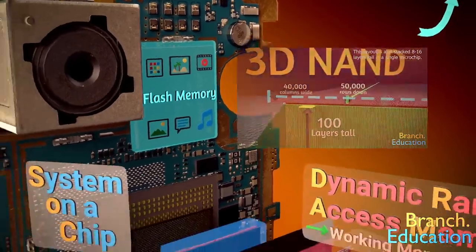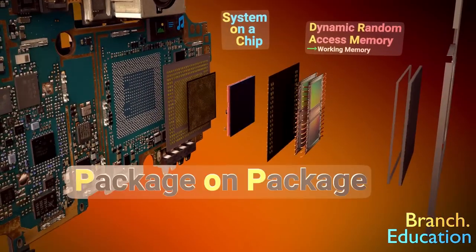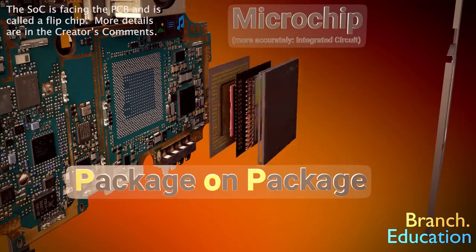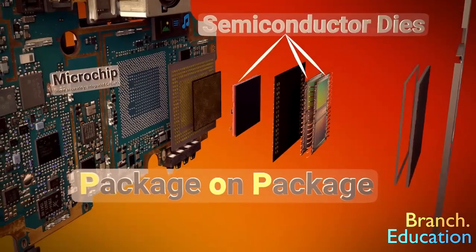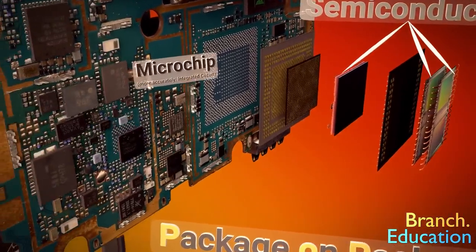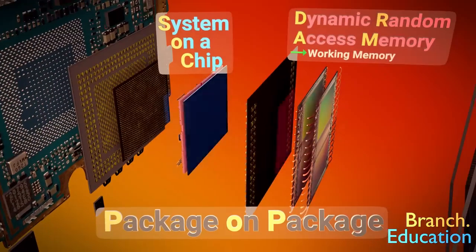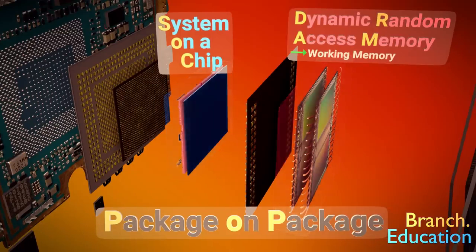But in this episode, we're going to focus on the SoC. This setup is called a package-on-package microchip, or POP. Technically, this is the microchip, and the separate layers of the DRAM and SoC are each called a die. However, the word chip has evolved to mean a variety of things. So, while all of these rectangular components are microchips or chips, both the DRAM and System on a Chip are also called chips, even though they're just half of the overall package-on-package microchip.